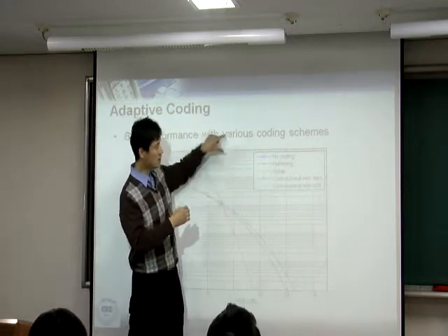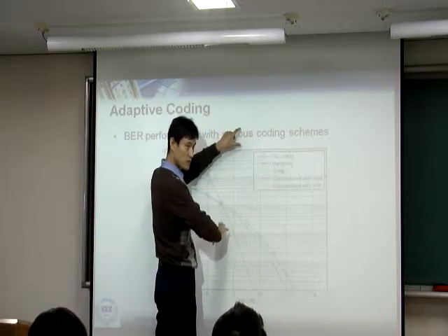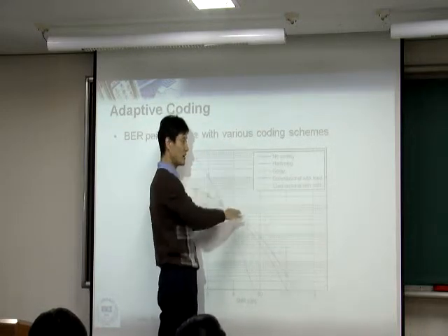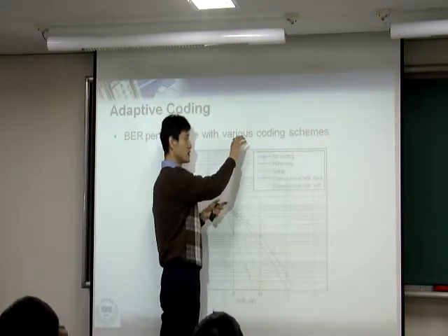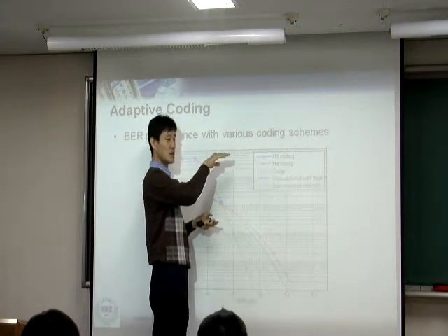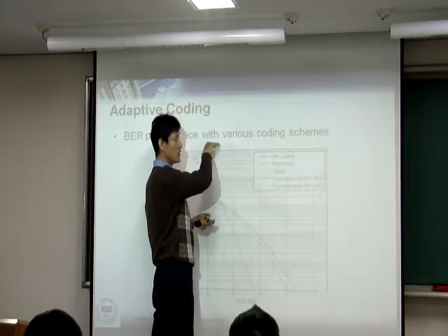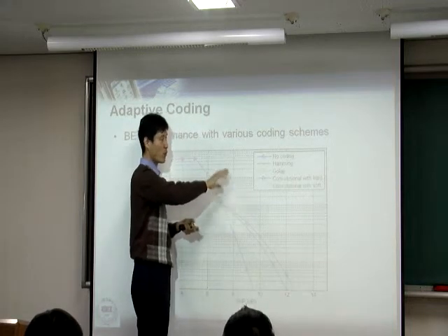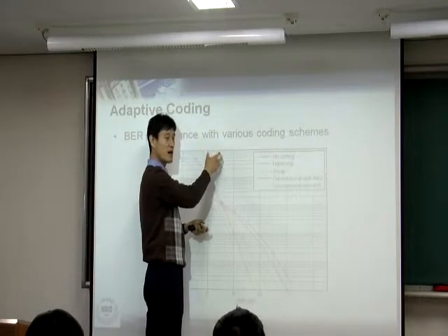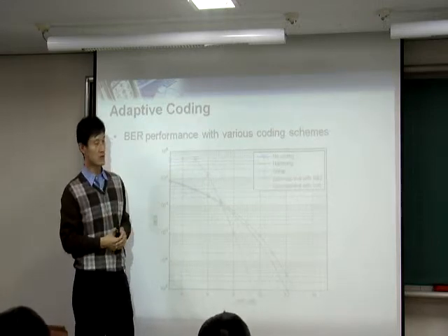You have a convolutional coding here, another convolutional coder here. If you want, you can have multiple of them, but all these things are parallel. But if you just do a parallel, then all these encoders are making the same outputs, right? That's why when you're feeding the information, on the first convolutional encoder, you feed the information as it is. When you go to the second encoder, we do a randomization of the information. Okay, then the randomized input sequence is going to the second convolutional coder. That's how the turbo coder looks like.